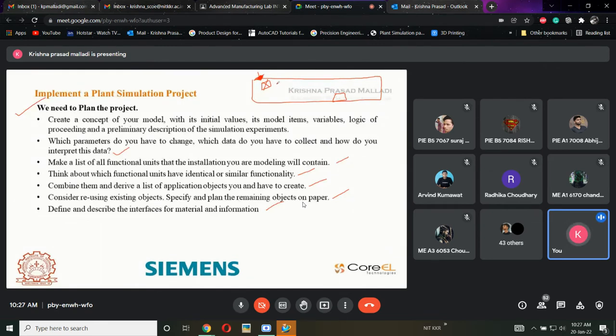If at all something needs to happen, it should be like a process layout, but the machine need not be moved from this location. I need to collect the inputs. What are the different things that are fixed? What are the different things that I need to consider? What are the different functionalities that I need to integrate? For instance, I have given conveyors between every station, but in actual the company does not have that much fund to add all the conveyors.